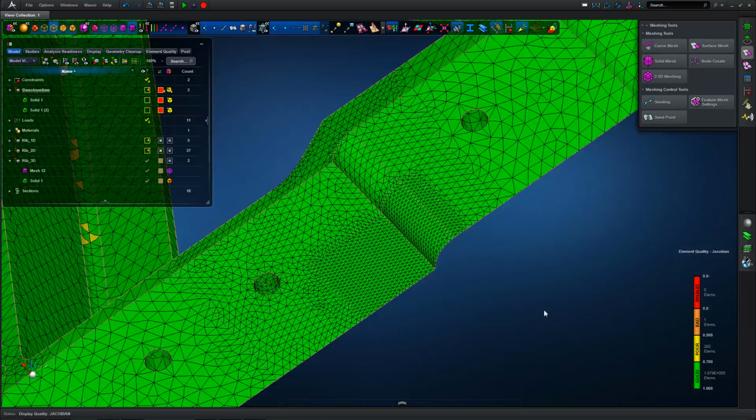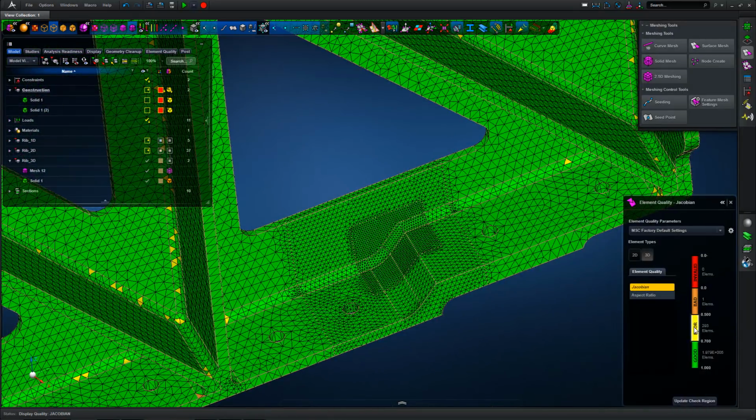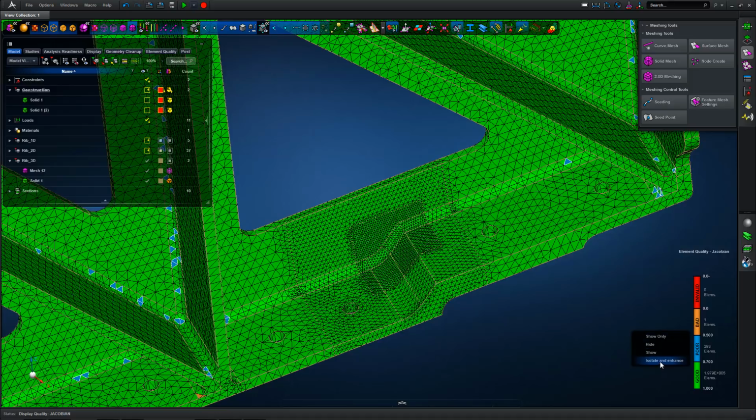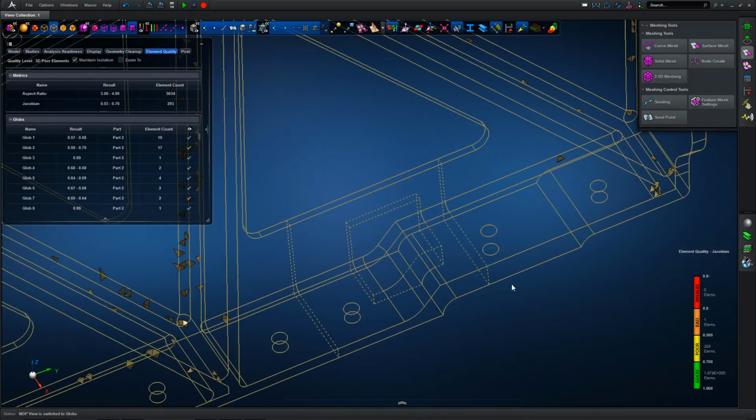We've got no bad or invalid elements for the full extent of the rib, and we're dominated by good quality elements at the region of interest. If we look at the poor elements, there are no poor elements in that local partitioned region, so we've got good quality everywhere we want to take results from, potentially within the model.